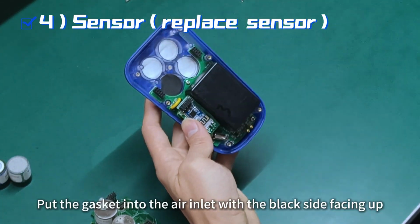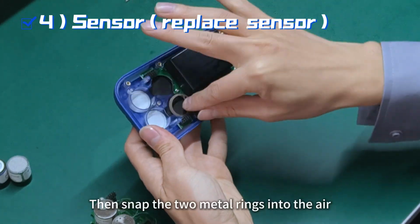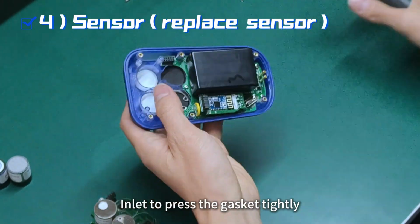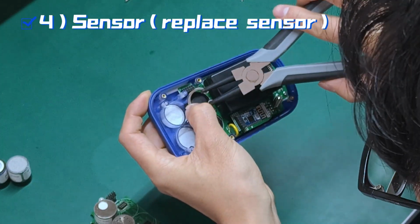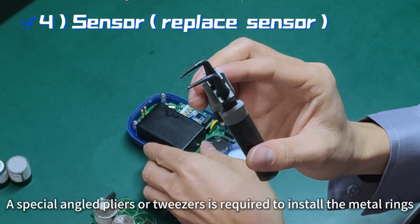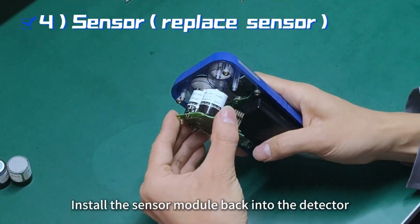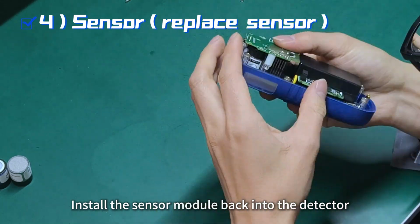Put the gasket into the air inlet with the black side facing up. Then snap the 2 metal rings into the air inlet to press the gasket tightly. A special angled pliers or tweezers is required to install the metal rings. Install the sensor module back into the detector.